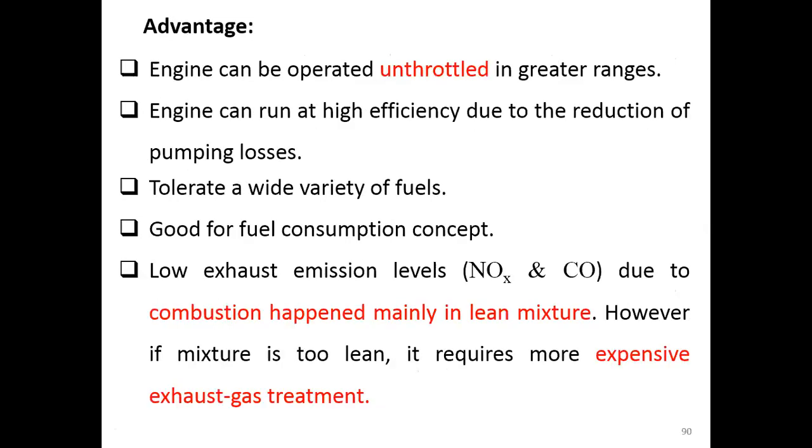Okay, so since they can avoid all of this, the advantage is that the engine can be operated unthrottled in the gate range, or in other words, maybe in the full range of engine operation. The engine can run at high efficiency due to the reduction of pumping loss. We don't need to provide as much work to draw the air into the chamber. It can tolerate a wide variety of fuels.